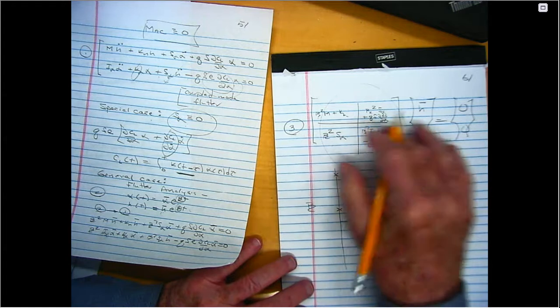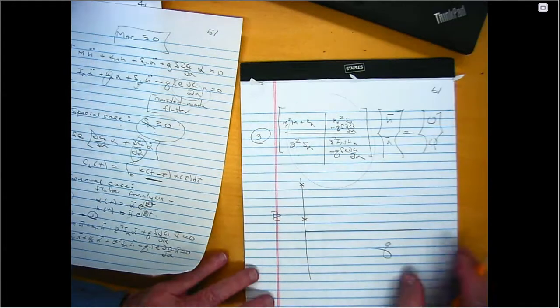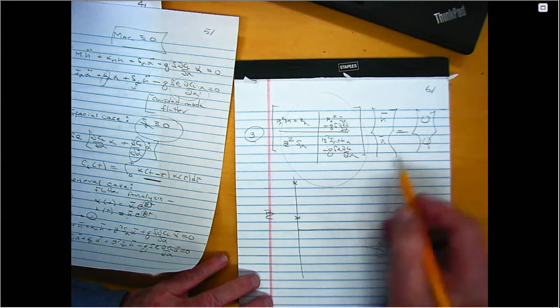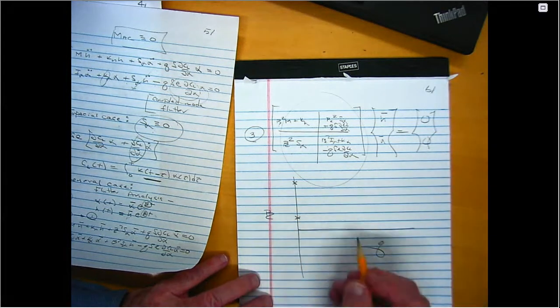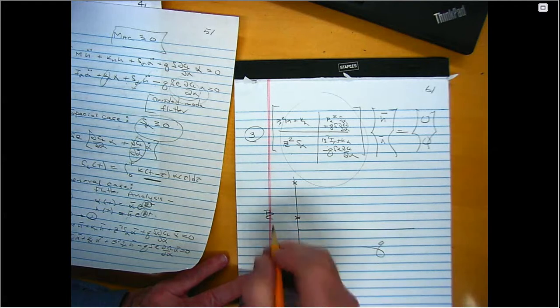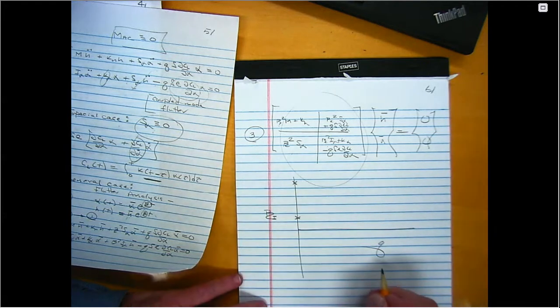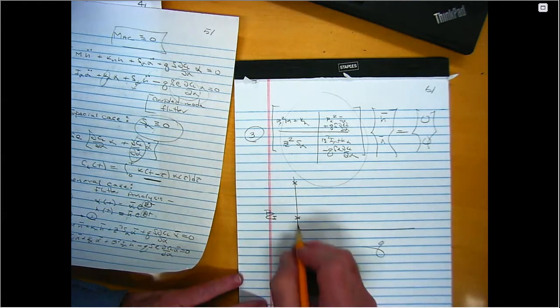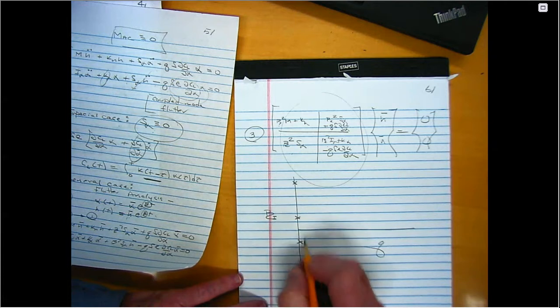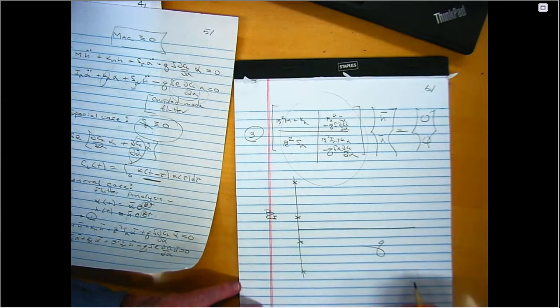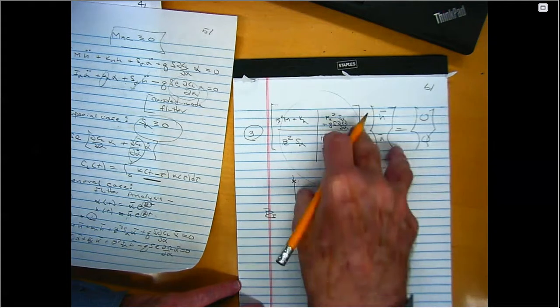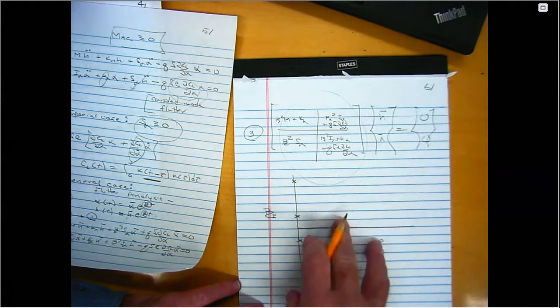Since I've omitted all damping in this system, the betas will be purely imaginary numbers to begin with. Okay? And they will appear in conjugate pairs. So this one has its negative counterpart, this one has its negative counterpart. Usually people only plot the upper half because it's just a mirror image, right?